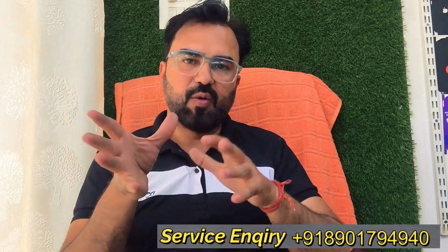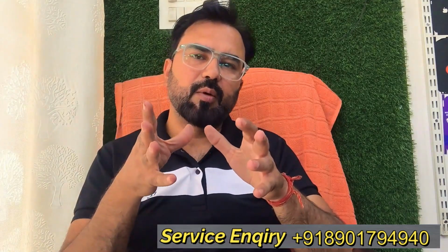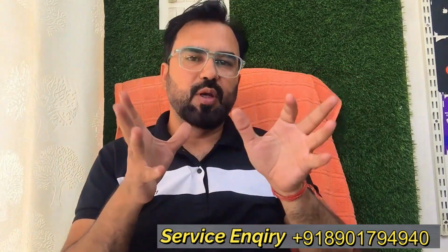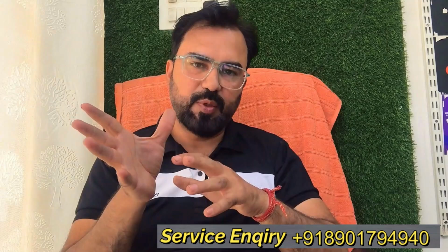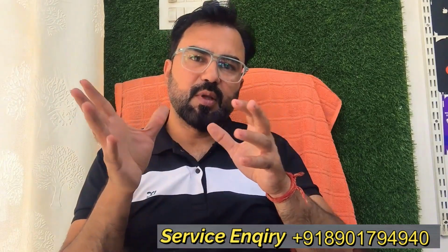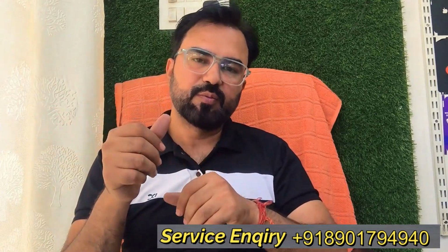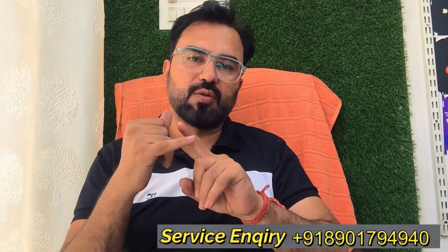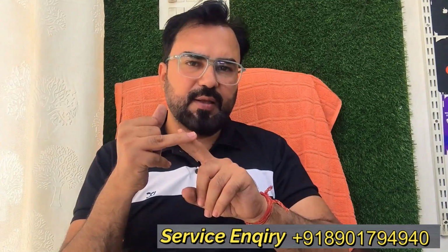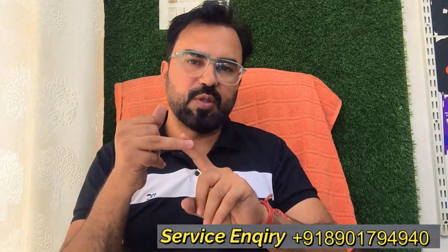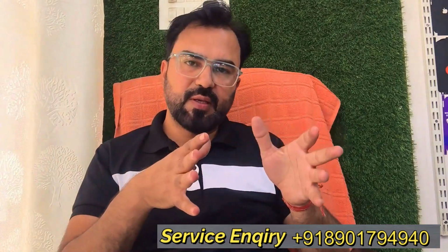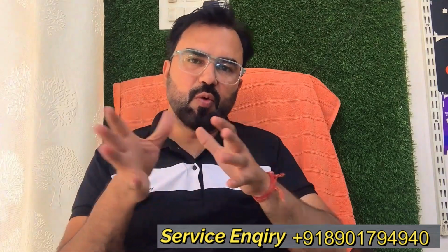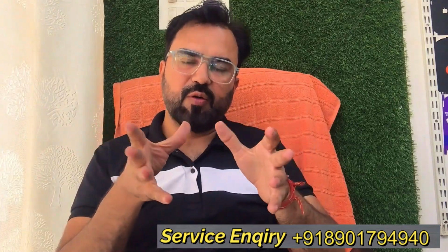Now back to the topic, the dead phone. As I already told you, this is a big topic. So we covered CPU related requirements. There are multiple requirements of the CPU, like frequencies coming to the CPU. If the frequency does not enter the CPU, your phone does not turn on. TX/RX lines are called communication lines. This is also responsible. The external bus interface lines, there are also many communication lines. The CPU also needs a buck section, a voltage requirement of the CPU.